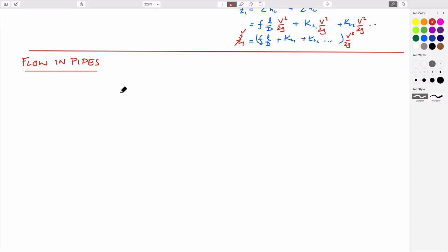Or you might want to know what the velocity needs to be to lift a person, and to figure out what the dimensioning of the pipes would be and the pumps that would allow you to get there. And so you can imagine that we might want to solve for those basic three things. So the basic three things might be geometry, and so for geometry, that might be the diameter of the pipe, it might be the length of the pipe, it might be how rough that pipe is. We talked about this on the Moody charts.